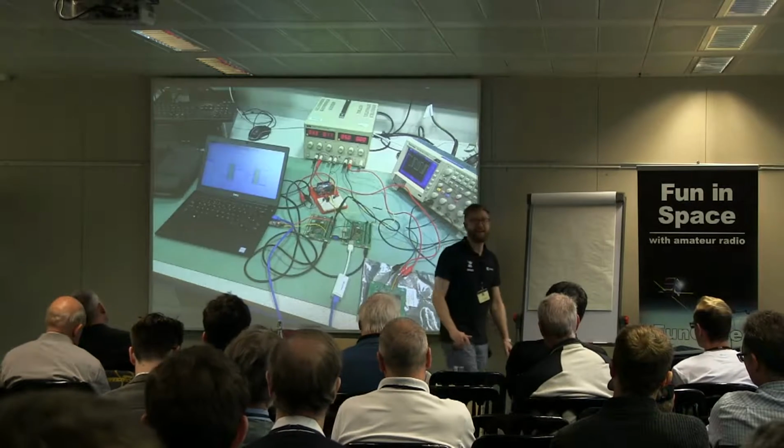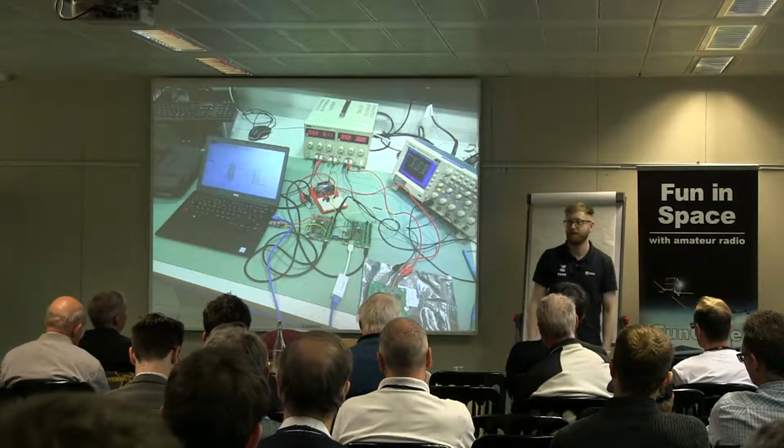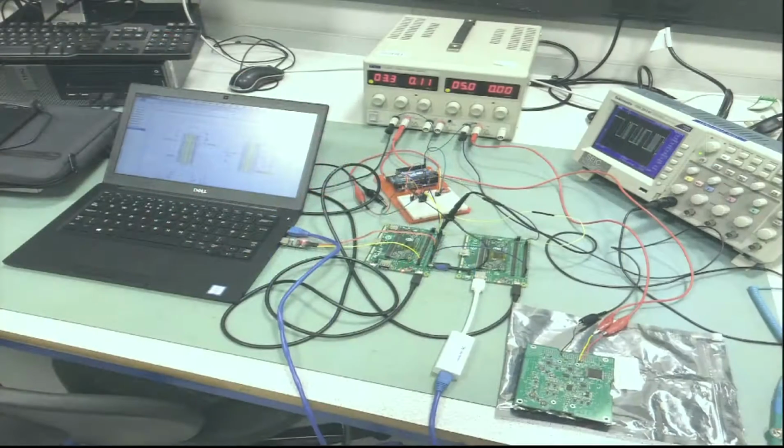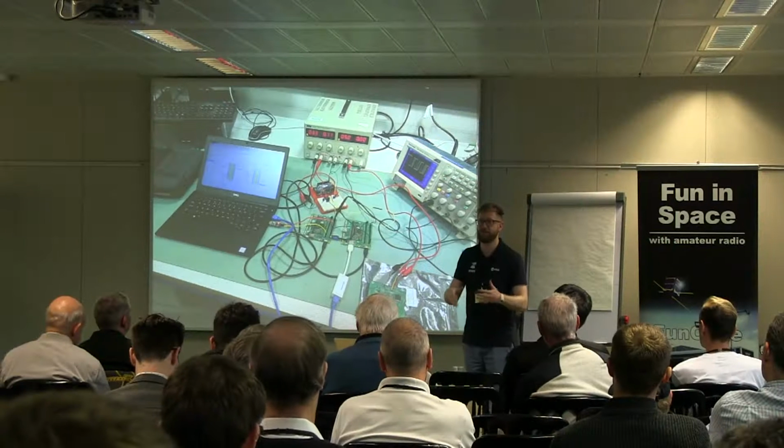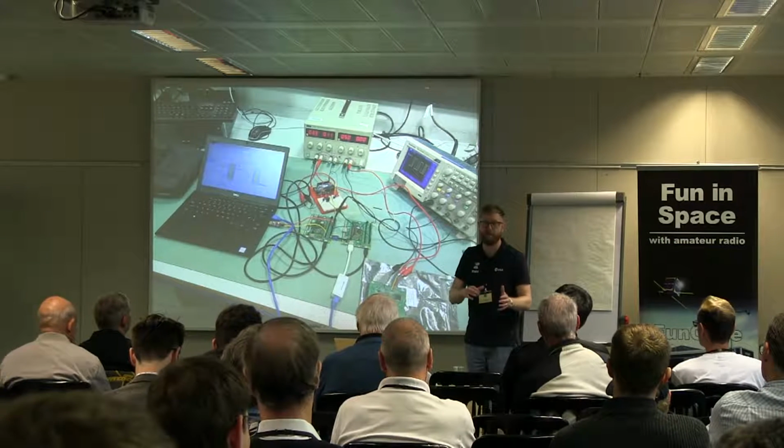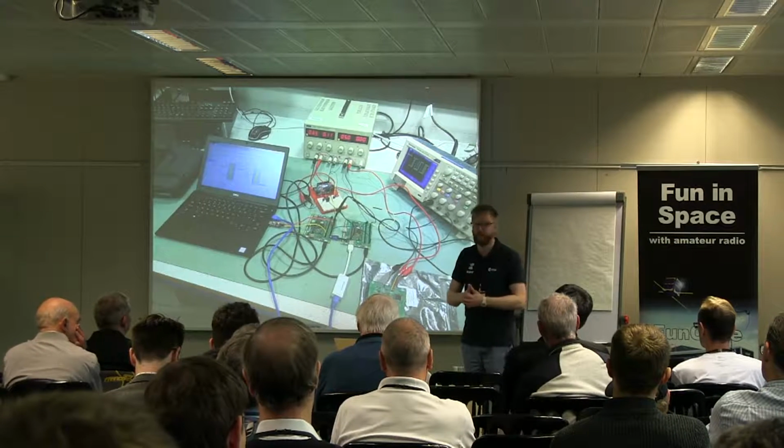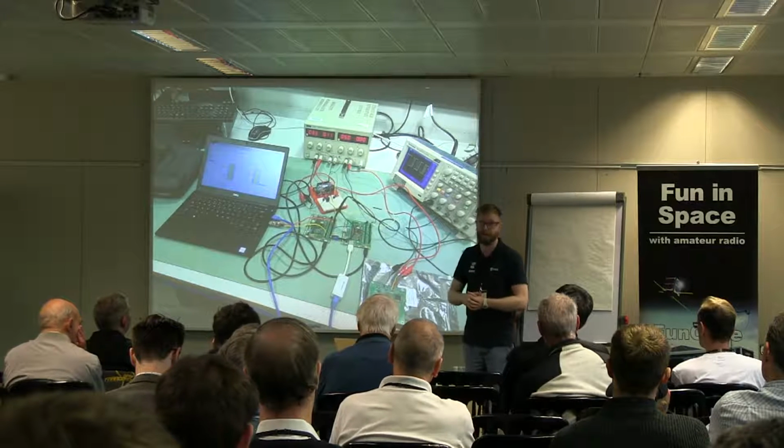It was a 2.2 ohm resistor that should have been a 2K2 ohm resistor. There were 5 of them that then just ruined everything. Finding it was awful, going and measuring loads and everything. We didn't really see it on a lot of the power circuitry because there wasn't much of a drop on it. But for the bus itself, yeah, big headache.